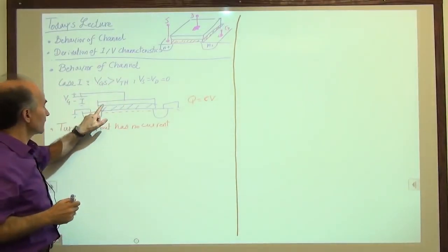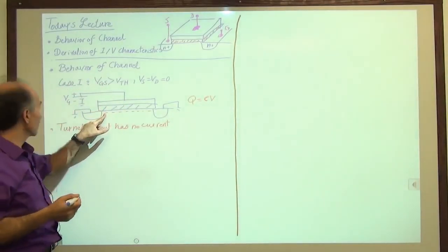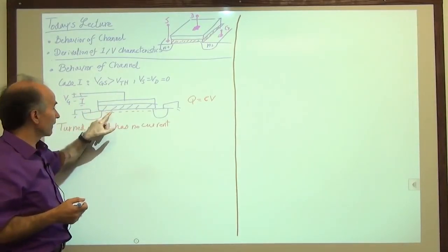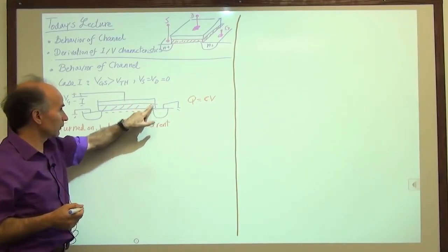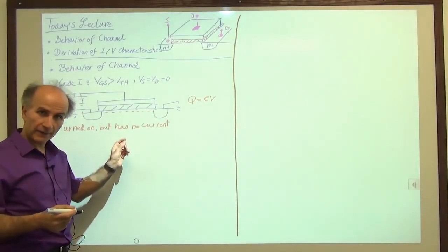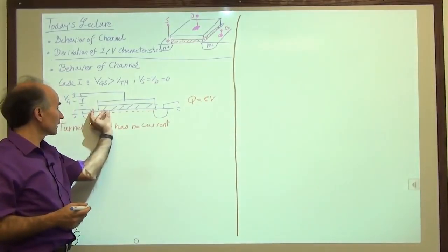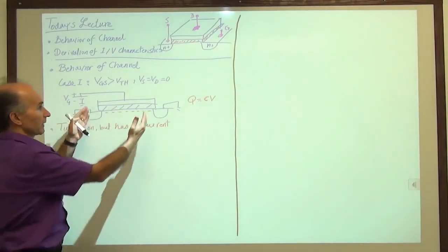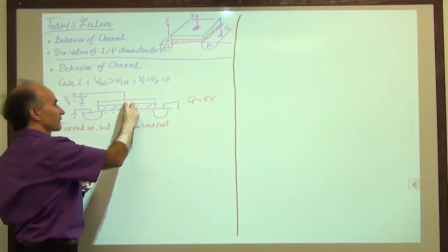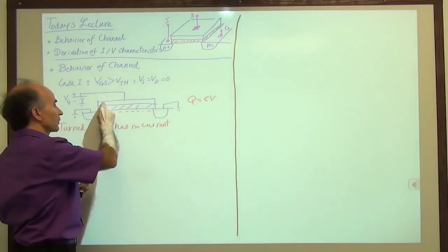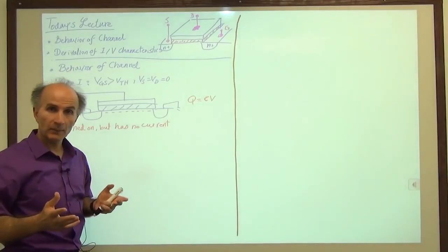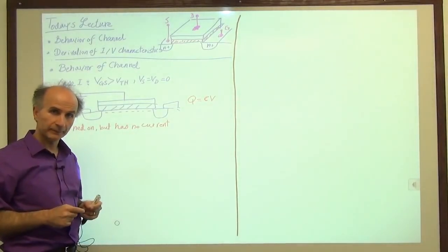So if I measure the voltage difference from here to here, it's some amount, right? So let's say 1 volt. So I have 1 volt from here to here. Then I have 1 volt from here to here, and from here to here, and from here to here. It's all the same voltage difference. Therefore, the electron density, the amount of charge that we have for each of these little capacitors is the same, right? If you break this capacitor into smaller units, we see that for each of them, we have the same voltage difference, and therefore the same positive charge here and here, positive, negative, positive, negative, positive, negative. That seems obvious, but we need this to go to the next step.